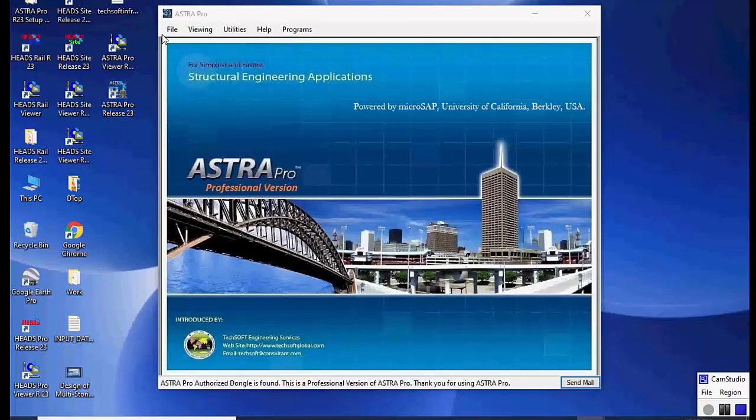The work includes structural analysis of frame, design of RCC floor slab, RCC or steel beams and columns, staircase, foundations as open, pile or raft in limit state method. The analysis is first done with structure configuration data, boundary conditions, and loading with option for applying seismic force. Obtaining the forces in the members, we shall get the design of the various structural components of the building. Finally, the set of editable CAD drawings will be created for construction.